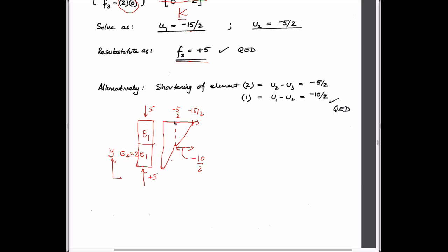And so what it's saying is that the deformation that occurs in this top component here is actually twice as much, 10 versus 5, as occurs here. And that's exactly what you'd expect, right? If this is much stiffer by a factor of 2, then it would deform less. And so we could calculate exactly what the amount should be, just by using Hooke's law. Of course, the magnitude is huge, right? I mean, the modulus that we're using, E is equal to 1, A is equal to 1, L is equal to 1, shouldn't be used, because modulus is typically a very, very small number.